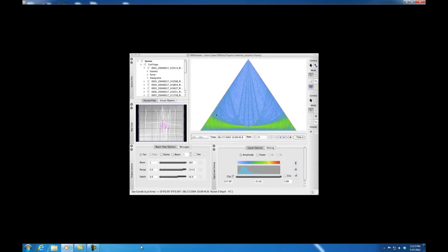Again, in the window, same look and feel. We always have the overview of the map view, in this case on the bottom left. But you'll see for the sensor, there's the fish trap subfolder again. And when it rescanned for Midwater and extracted more information, it gets the details into the sonar datagrams that weren't required for Bathy processing within DMagic or for the backscatter processing in GT. But they are required for Midwater. So there's more information within the same area, put into the metadata section of the files in the project.